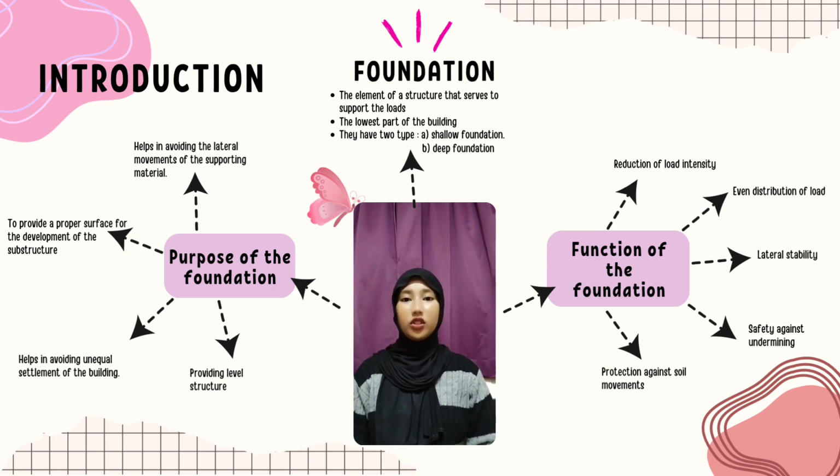Function of the foundation. Based on the purpose of foundation in construction, the main functions of the foundation are, first, reduction of load intensity. The foundation distributes the load of the superstructure to a larger area so that the intensity of the load at its base does not exceed the safe bearing capacity of the subsoil.